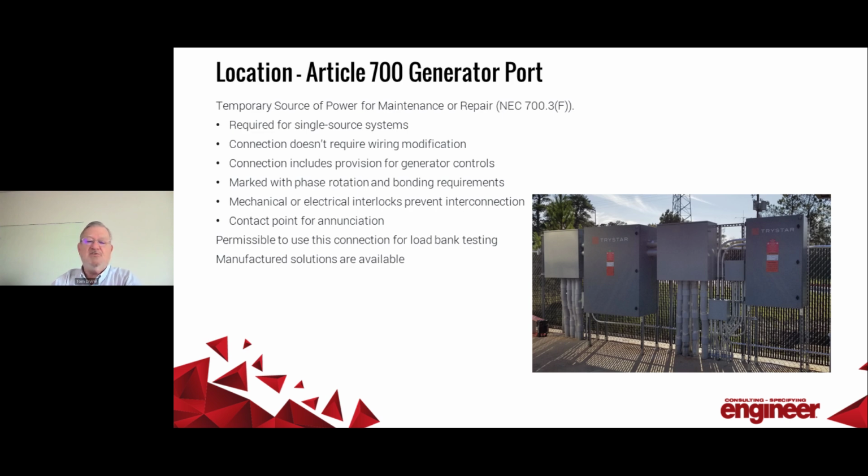And this slide shows two generator ports, one for the emergency system and one for the rest of the building. This is a whole building supported by standby project. This was actually a forensic laboratory where autopsies are performed. They wanted to be able to support everything in the building, but we had to have two transfer switches for that. They are an off-the-shelf product made specifically for this application.